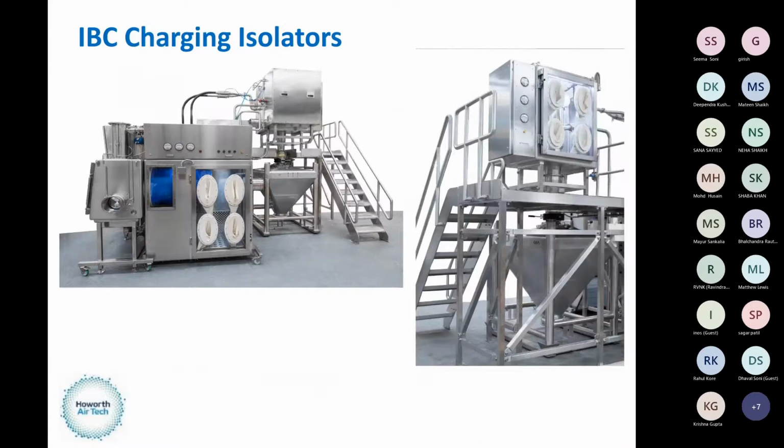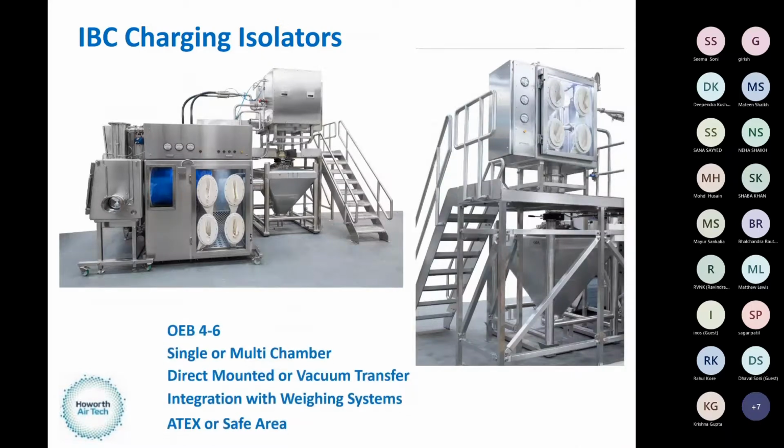Another common process now is IBC charging. So for your tableting phases, for your blending phases, we need to get those materials into that IBC. We're not just handling APIs here, we can be handling the excipients, so the lactose or the different materials will perhaps need to be charged in stages. So we create like a sandwich within that IBC.